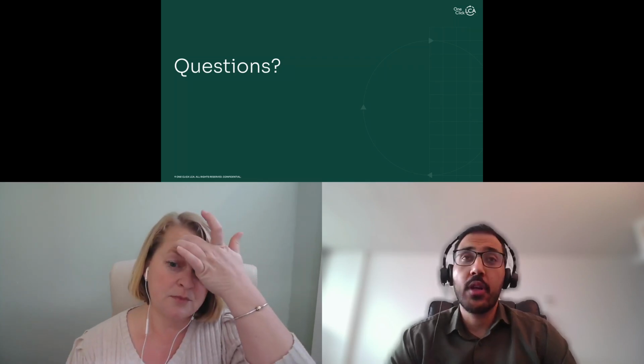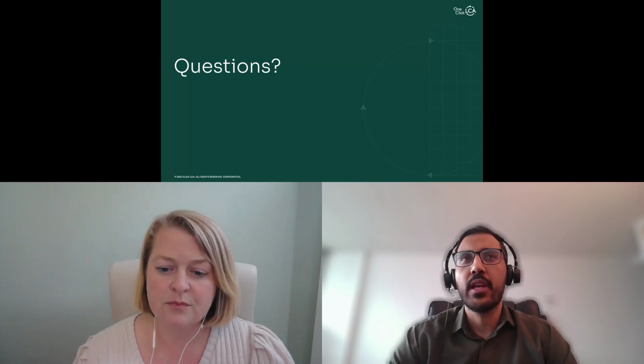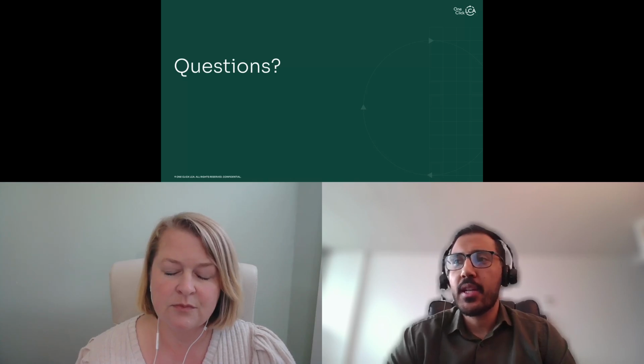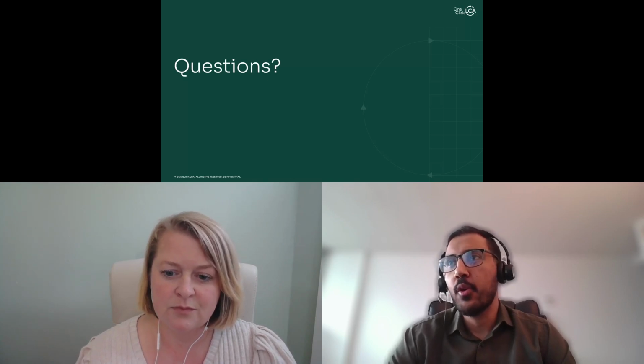Great. Awesome. Thank you. And then is it mandatory in LEED V5 to track the construction site operation emissions, or A5? So the answer is no. You can go forward with the embodied carbon assessment of A1 to A4, B1 to B5, and C1 to C4, and you can have up to 6 points, so that's fine. Or even if you have 3 points, 4 points, you can follow up with the EPD option and achieving the rest of the points.